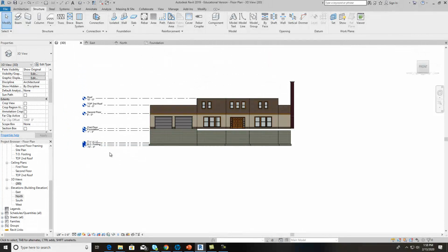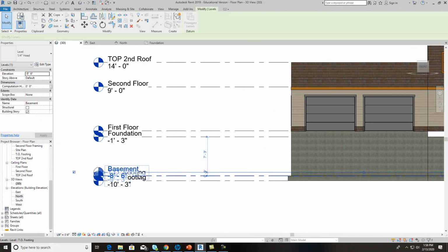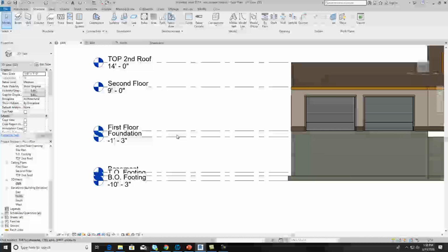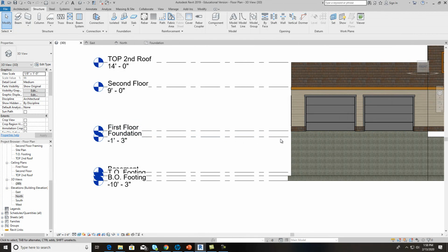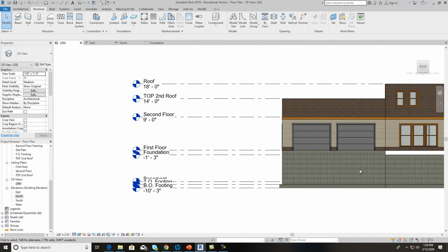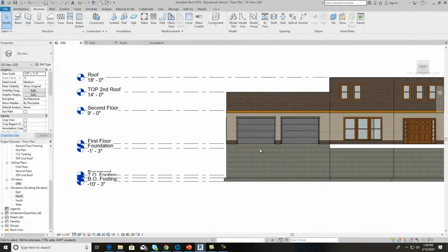And what I was talking about earlier, remember I was talking about the clip plane? If I look at this thing straight on, right here is that foundation. That's where the clip plane was before, and it was going down minus, I can't remember, 10 foot, but I had this one going, and I think the clip plane was at 0. It was at foundation 0, or it was first floor, I can't remember. But I just dropped it to minus 5, and then it was actually cutting through down here so that you could see it on the plan view. So this is how I've got it at this point. We might have to drop this wall down. It just depends on what the book wants us to do, but that's what I would do if it was me.